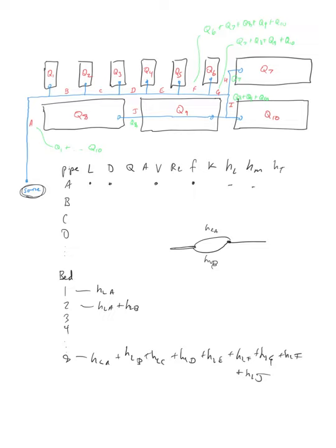What's happening in an irrigation system like this is that we're delivering water essentially in parallel to a bunch of points that are at the same head. And what is that head? Well, it's atmospheric pressure. So a way of thinking about it is it's like a parallel pipe system, but we are always delivering to the same pressure, atmospheric pressure.